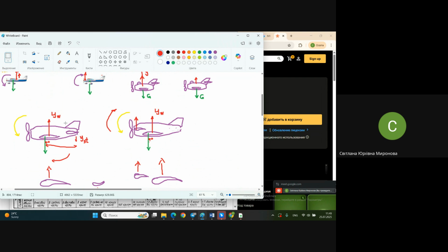Practically, there is no distance between wing and stabilizer, and in this case, you can't. The whole stabilizer practically should be equal to the whole elevator. Either you place a huge stabilizer, with an elevator, or you are forced to use all the surface of the stabilizer as the elevator from time to time.